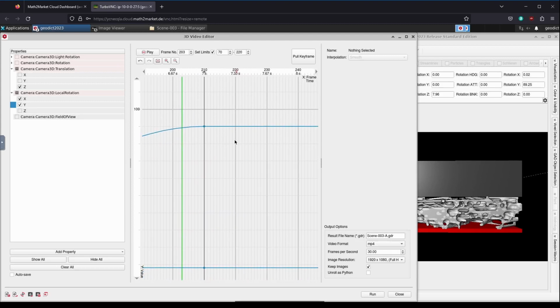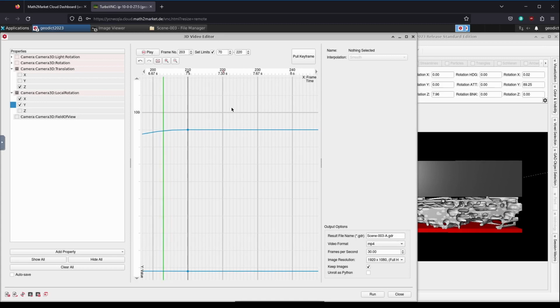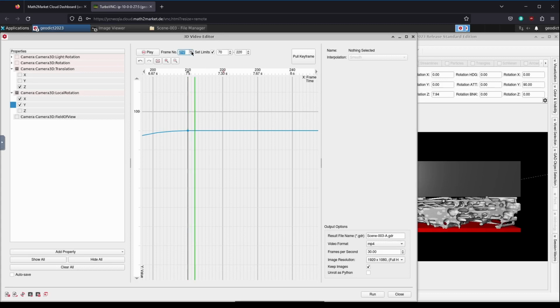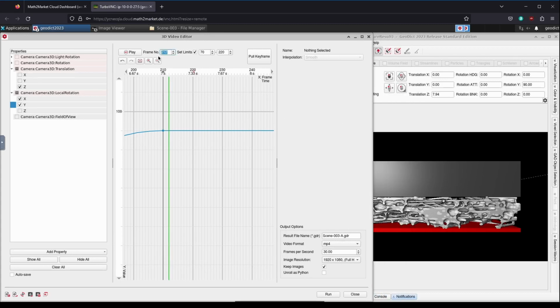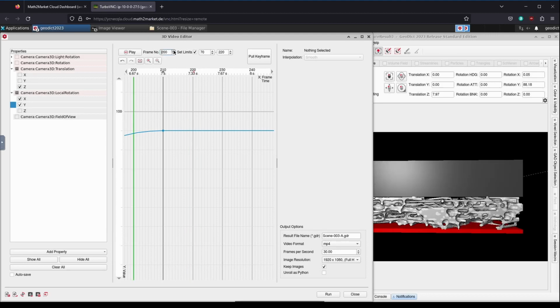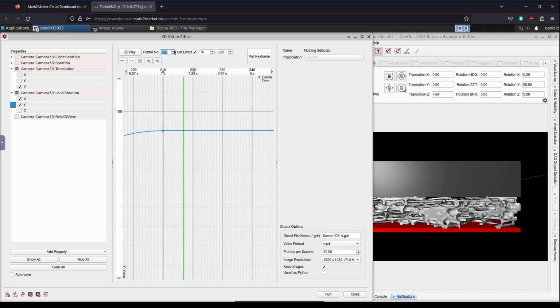That's why I'm zooming in real close here and using the numerical positioning of the playhead to go through the animation slowly, step by step. That way we can get a feel for the timing we need to apply here. I'm clicking through the frame slowly but at a steady pace. Okay, so we want to keep the oversteering and rocking to a minimum, around 20 frames. So 20 frames later, at frame 230, we're going to create a new control point.